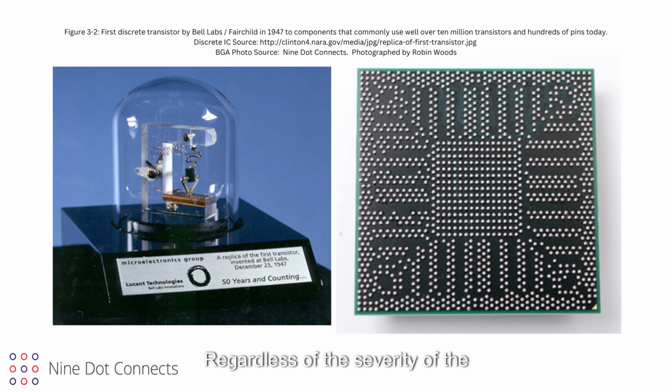Regardless of the severity of the modifications that are necessary, often at least 2 weeks will be lost in making the fixes to the PCB design, sending the new design through fabrication, and then returning it back to assembly. Most of the design mistakes could have been avoided by simply knowing the processes used in the assembly house.